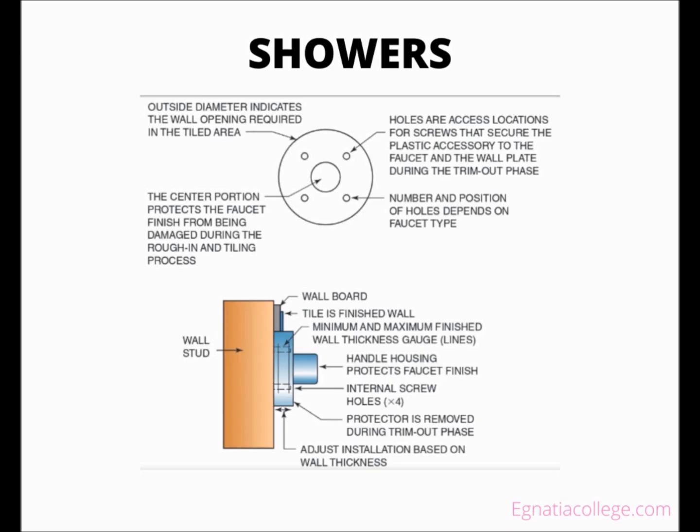The center of the faucet is usually centered in the shower. One-piece shower units may have a dedicated area to install the faucet. Handicap showers have factory-installed grab bars, with the faucet placed in a dedicated area above them. Some showers have handheld spray units and multiple shower head features that dictate the placement of flow control devices and valves. The actual installation is based on job site conditions and manufacturer's instructions.